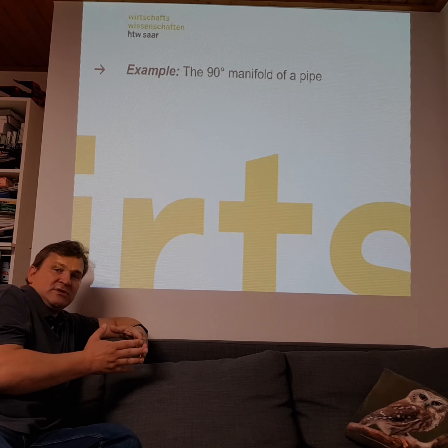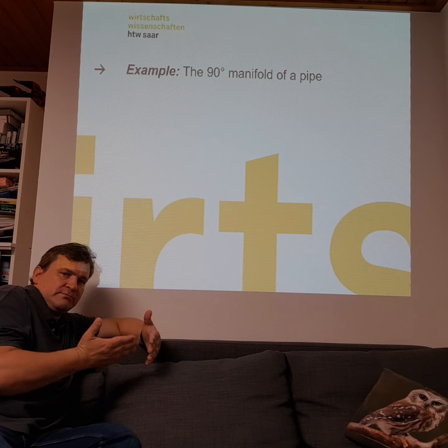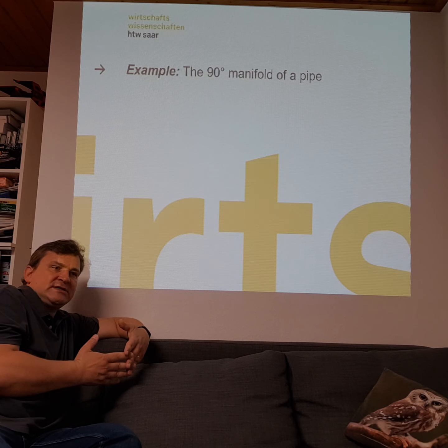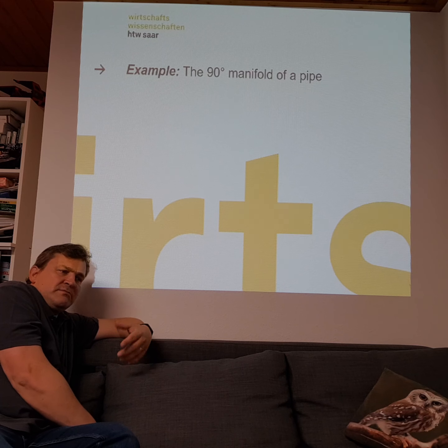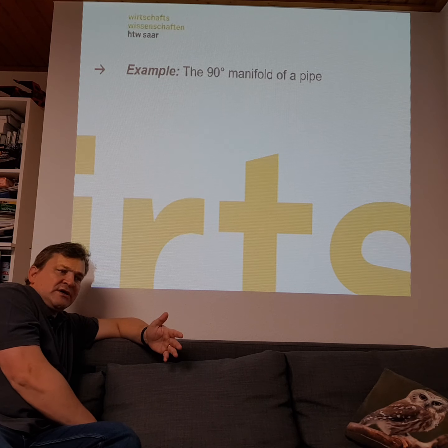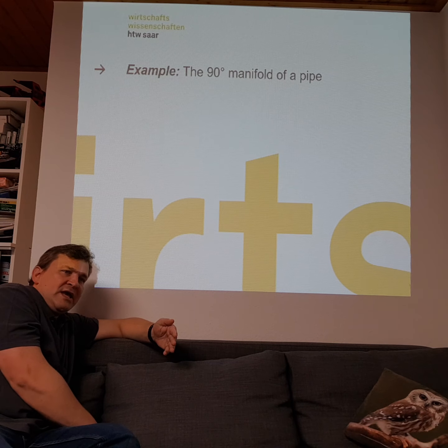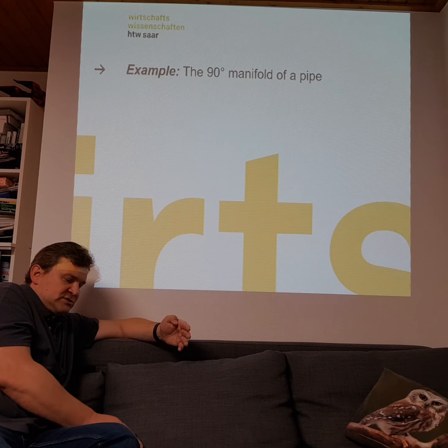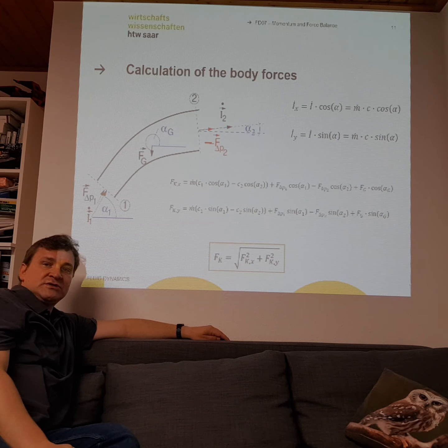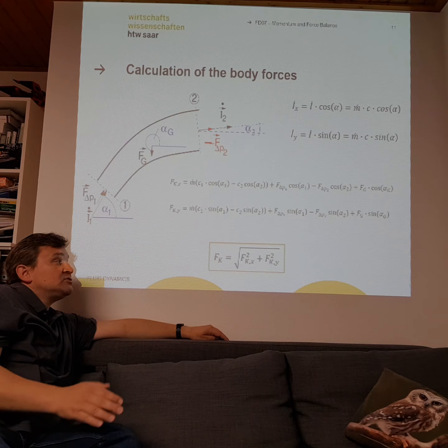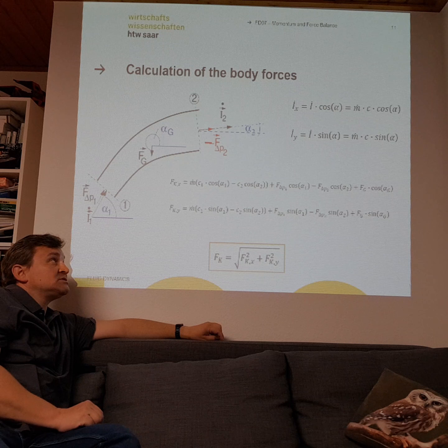And the next example is not a plate, but it is really similar to our plate example, and it is a 90-degree pipe element. That's also an important calculation for fluid dynamics. In many cases we have pipes, water pipes or gas pipes, and if water or gas flows with high velocity through this pipe, we get a force on the walls, and we need to know how to calculate the forces on the walls.